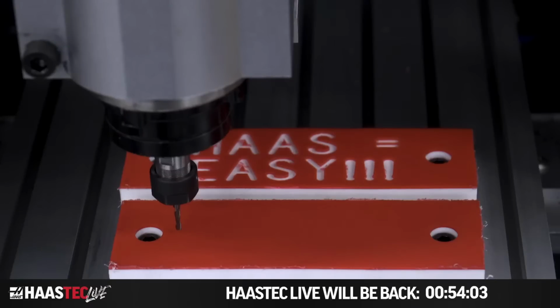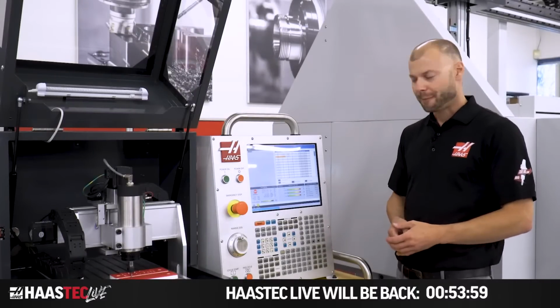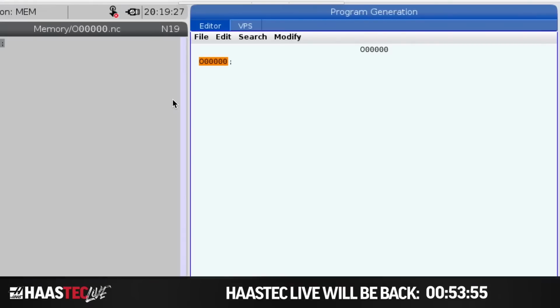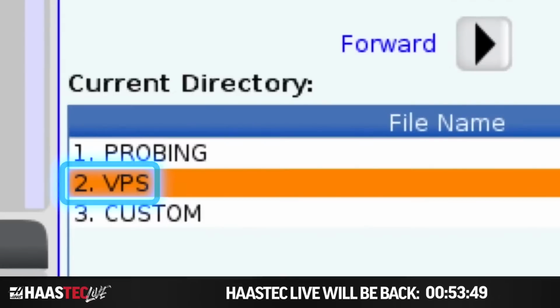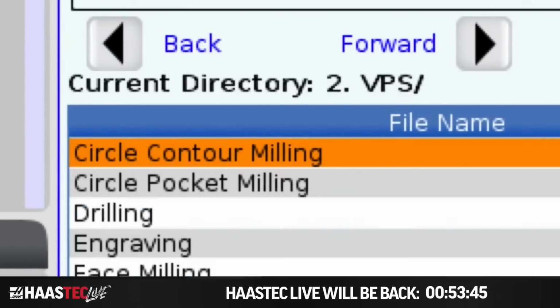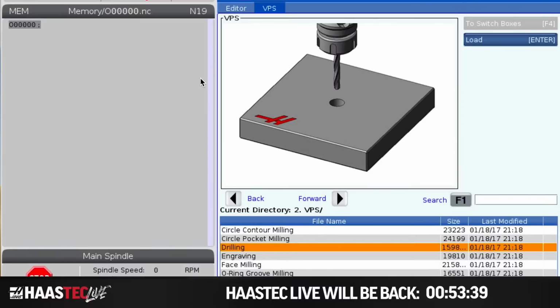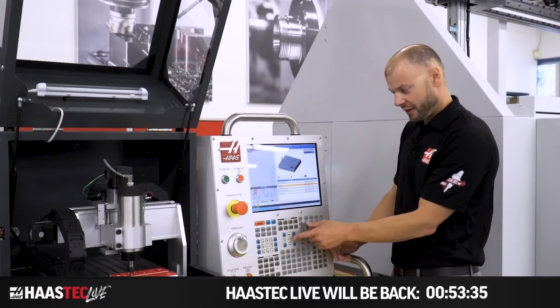Now that I have my X, Y, and Z established, let's go to VPS and make a short program. You can find VPS under the Edit button, then tab up to the top and over to VPS, and then go down to the VPS. And we'll go over. As you can see here, you have a few different shapes we can easily make, like bosses, pockets, drill patterns. But today, I think we'll do a little engraving.